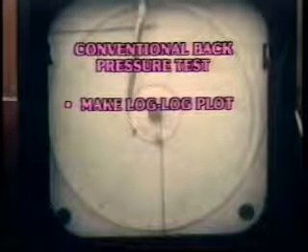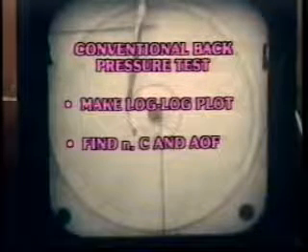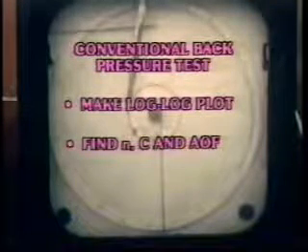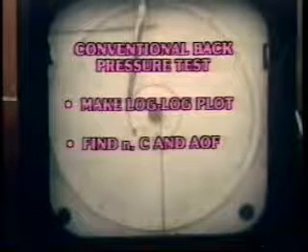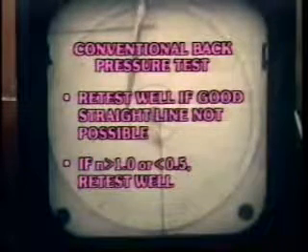The standard log-log plot of the 4 points is made, and values for N and C determined, as we pointed out earlier. The AOF is found by extrapolation or calculation. If a good straight line cannot be drawn between 3 or more points, the well must be retested. If the same condition exists upon retest, then the line through the best 3 retest data points is to be used. If it is found that N is greater than 1 or less than 0.5, a retest is necessary.